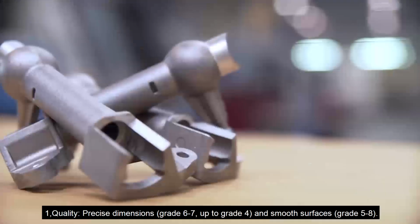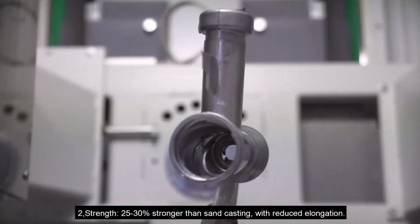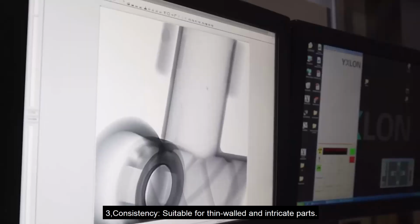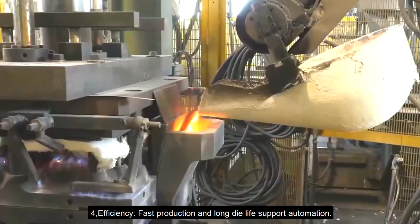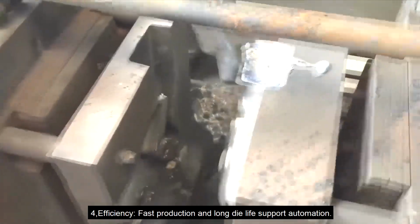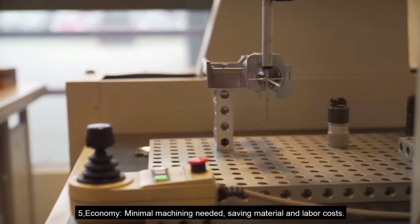1. Quality: precise dimensions and smooth surfaces. 2. Strength: 25 to 30% stronger than sand casting, with reduced elongation. 3. Consistency: suitable for thin-walled and intricate parts. 4. Efficiency: fast production and long die life support automation. 5. Economy: minimal machining needed, saving material and labor costs.